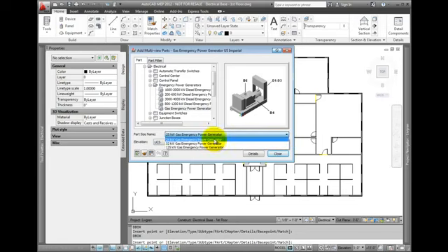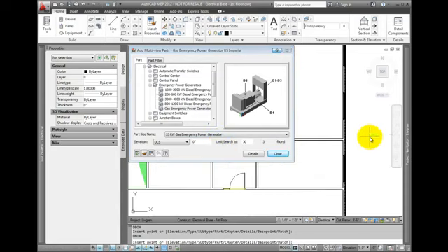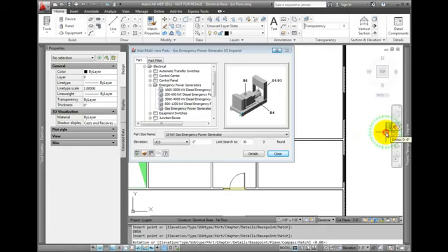For the part size name, select the 25 kW Gas Emergency Power Generator. If the dialog is pinned, left-click once in the model space area to place the part. Select a point on the east side of the building, outside of the storage room. The MEP compass will appear, showing the increment angles that can be used to place the part. Pick a point as shown, and then set the rotation to 180 degrees.